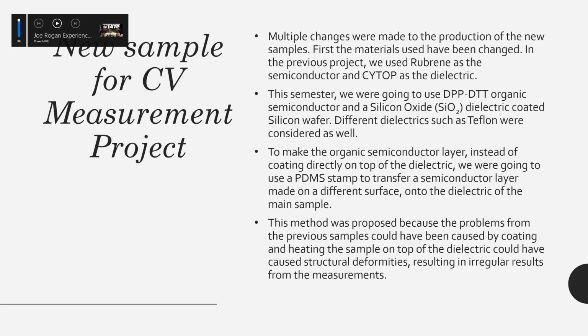This semester, we're going to use an organic semiconductor called DTT, and a silicon dioxide dielectric coated silicon wafer, like the one that was used for the IV measurement project. Different dielectrics such as Teflon were considered as well.